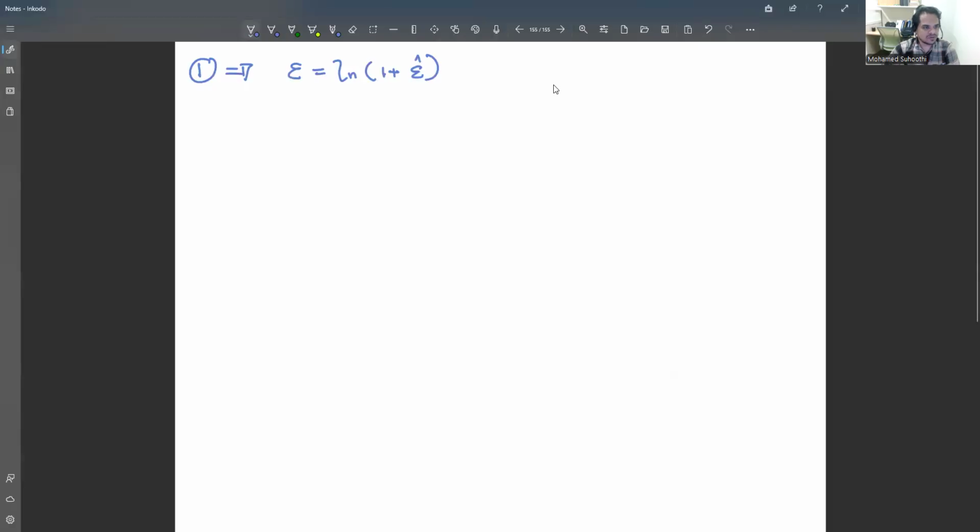If we convert to normal, that means 1 plus nominal strain equals exponential of this one, right? Okay. This is something you know, simple mathematics, right? So therefore from here, you know your nominal strain equals e to the power true strain minus 1, right? Okay. So these are the important points I'm going to tell you, right? The third one. Okay, I'll mark this one as equation number 3.